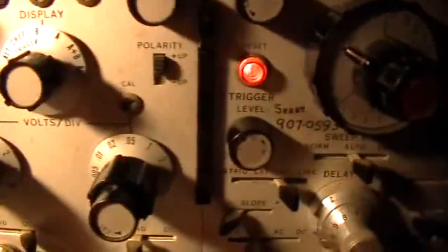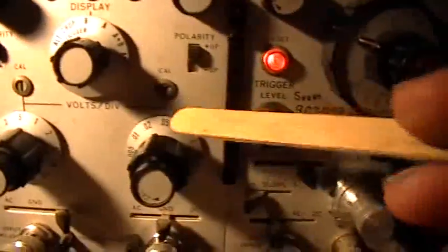And what I've done is I've set the 0 line right at, I tried to, hang on a second, let me see here. Okay, so I'm setting the 0 line right on that center graticule marker. Okay, right there, right on the center. And we're looking at this with the knob at 0.05 volts per division, so we have a 10x attenuating probe, so this is actually half a volt per division on the 0.25 ohm current viewing resistor.